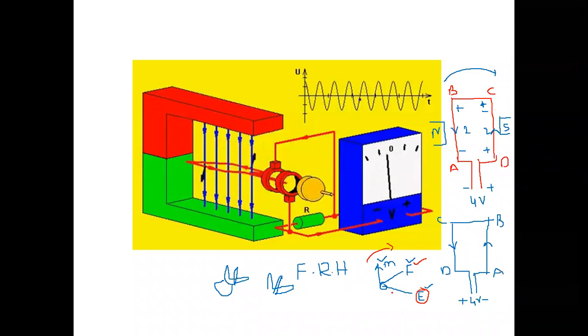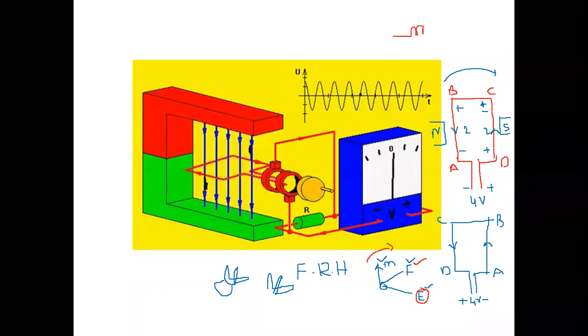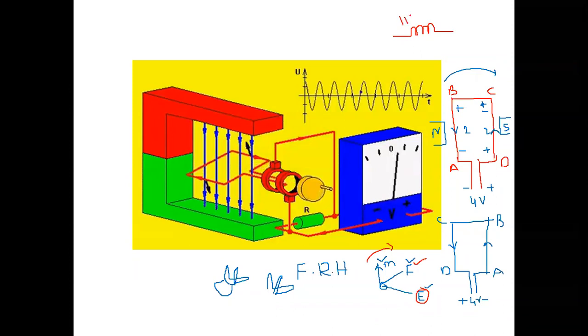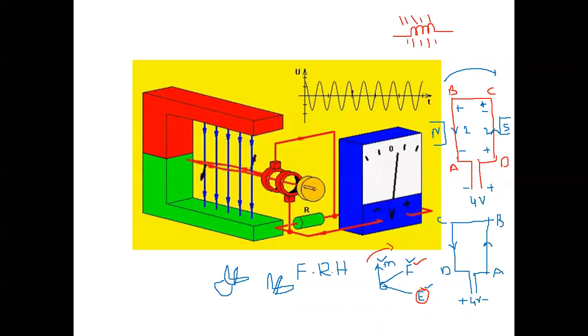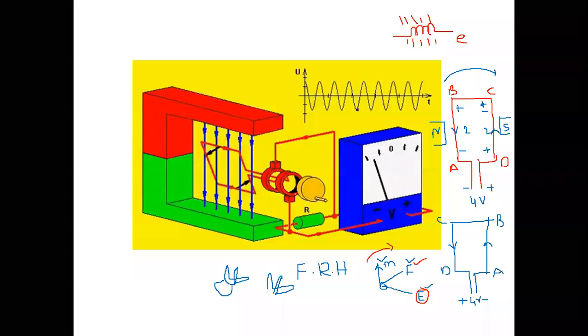Another law which is also used to find the direction of induced EMF, not exactly in a generator but in linear motion, or else for example where your conductor is not rotating but flux is changing with respect to time. Flux linking with the coil is changing with respect to time, so even then EMF will be induced. That direction of EMF is given by Lenz's law.